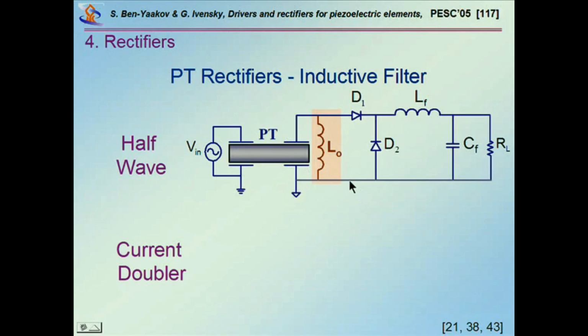you do have to add an inductor. Without an inductor, in this arrangement there is a DC coming off here, and obviously with no inductor, this DC will have to charge up this capacitor, and that will be the end of it. So you do need an inductor. It may not be a very nice solution, just having another inductor.